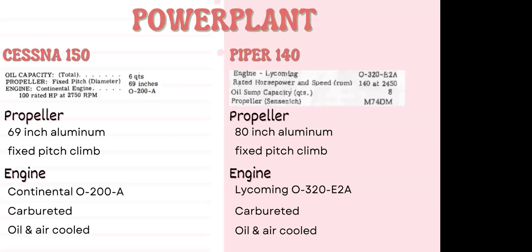But in this case, we're just oil and air cooled. So our oil serves dual purpose: to lubricate the cylinders, which also reduces heat, because nobody likes a little metal on metal friction. That's not good. And then air cooled through the intake as well as various other openings in the cowl to air the engine.